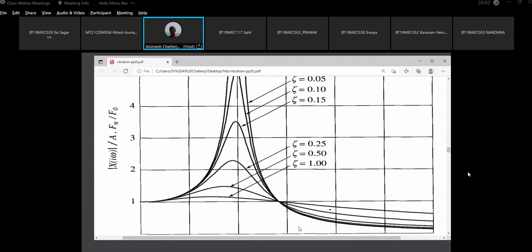So if I design for 1600 as 85% transmissibility, so if 85% transmissibility is achieved for 1600, for all other operating RPM, it will be better than 85%.